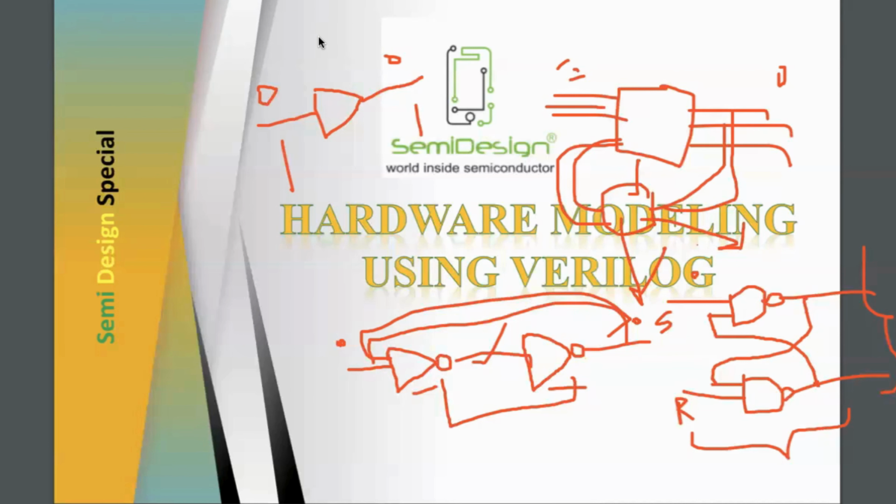So in Mealy, we have some glitches. At the output side, it will generate some glitches, right? So do you have any idea about that? Why it will provide the glitches and how we can avoid the glitches, and why Moore is preferred practically compared to the Mealy? Do you have any idea in that? Not yet. Okay, then you need to practice more on finite state machines.